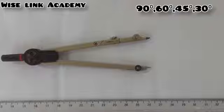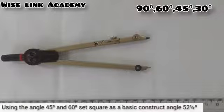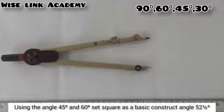Now my question is here. As you can see, the question goes below: using the angle of the 45 and 60 degree set square as a base, construct angle 52 and a half. Now my question is, angle 52 and a half falls in between which range? I'm having 90, 60, 45 and 30. So angle 52 and a half falls in between what? 60 and 45, right? As you can see my arrow indicating.